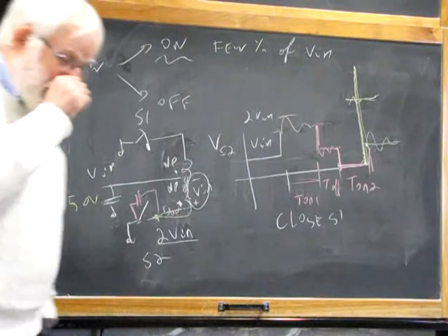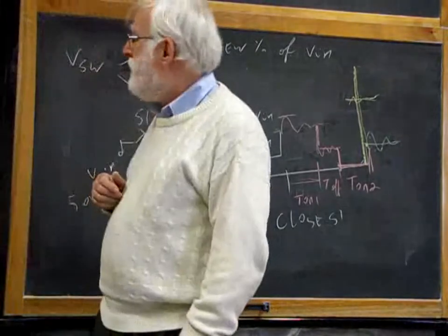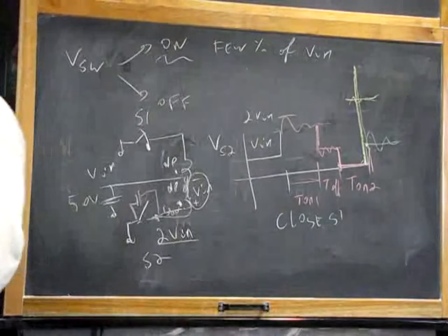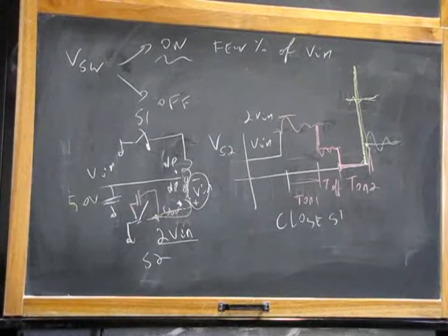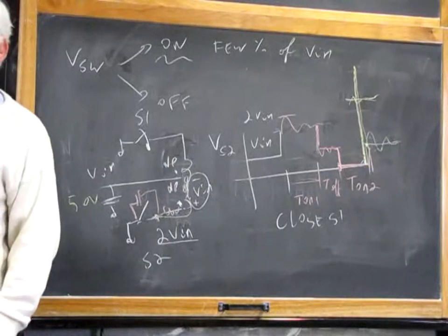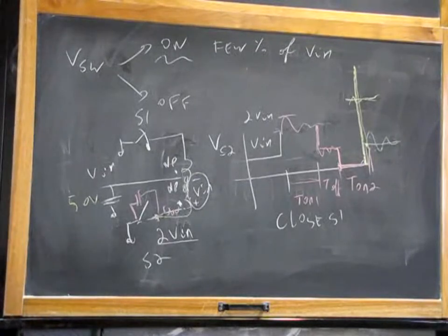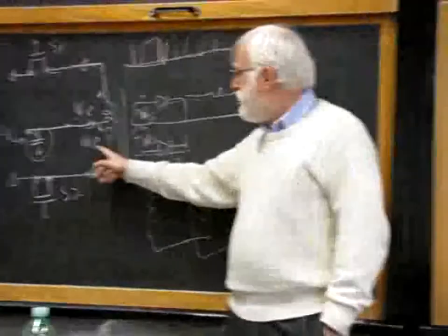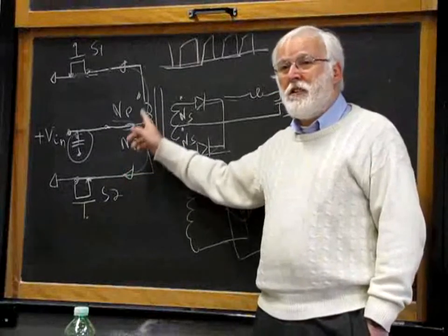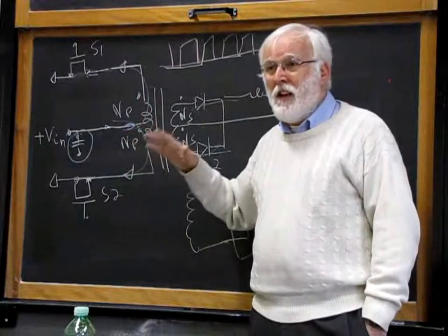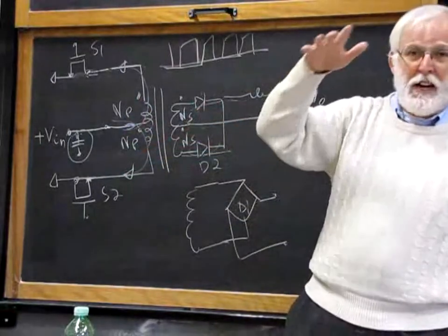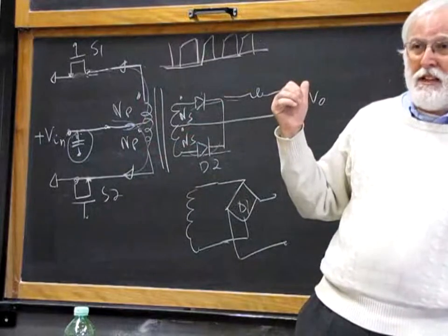For this kind of converter with a full wave rectifier on the output, that means you use completely the transformer, both with positive and negative pulses, you have to make sure that you don't apply a DC component on the primary side, because if you apply a DC component on the primary side, your fluxes start to run away and eventually the transformer saturates.